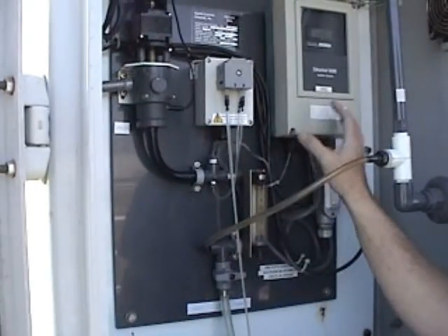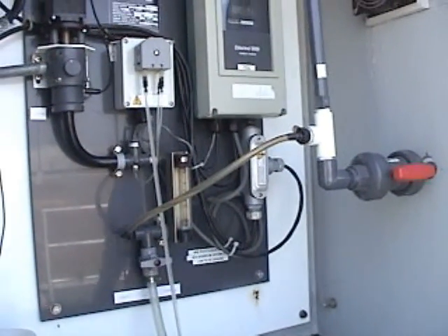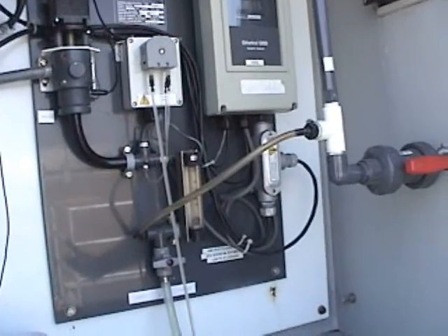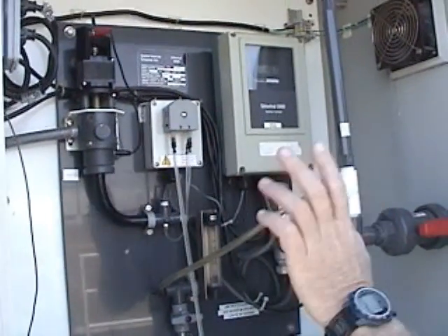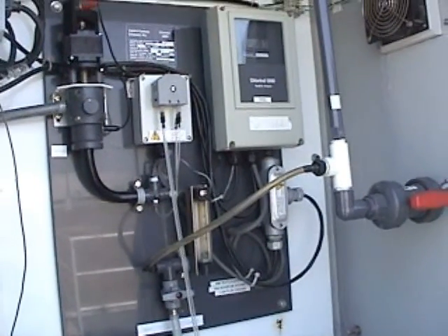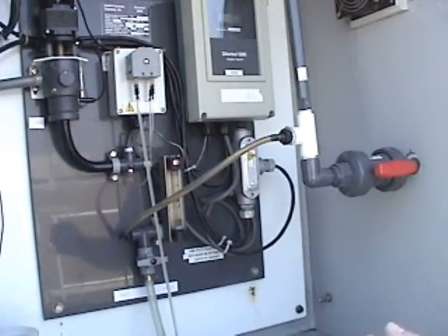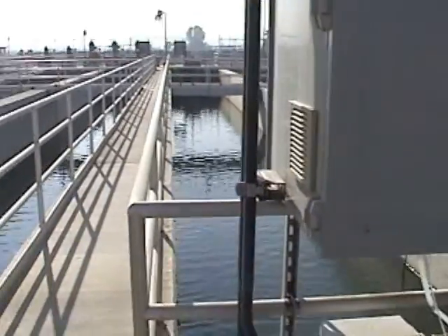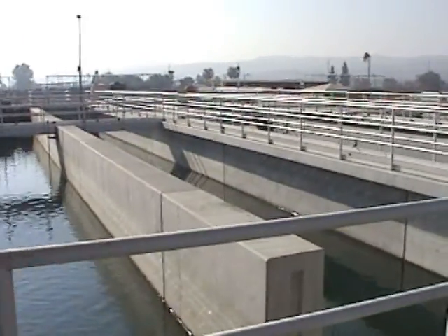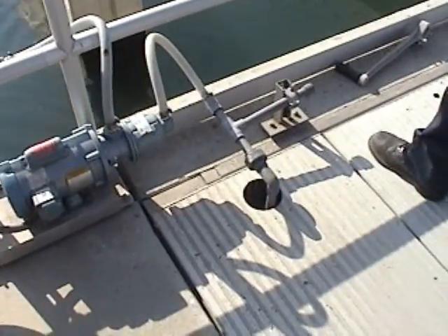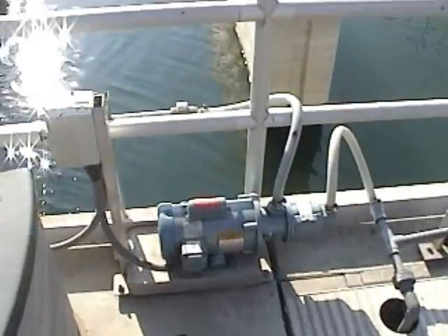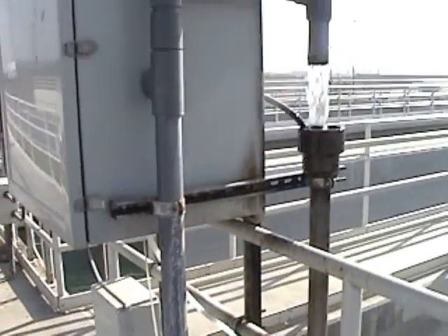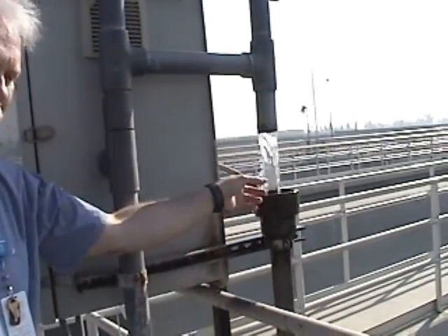During the daytime, if you have a problem with an analyzer, the best person to look at it is an instrument tech. You can try a few things yourself and help the instrumentation people out by doing that. But if you're not sure, or if that fails, you would go get an instrument tech. We have 2 analyzers on the influent side and 2 analyzers on the effluent side of the plant, and they're pretty important. Right here, this is where the sample is pulled up. You have east and west analyzers. If you were to have a problem with an analyzer, you could check this sample pump and make sure that it's pumping. You'll know right away if it's not, because this flow would stop if I shut off that pump.